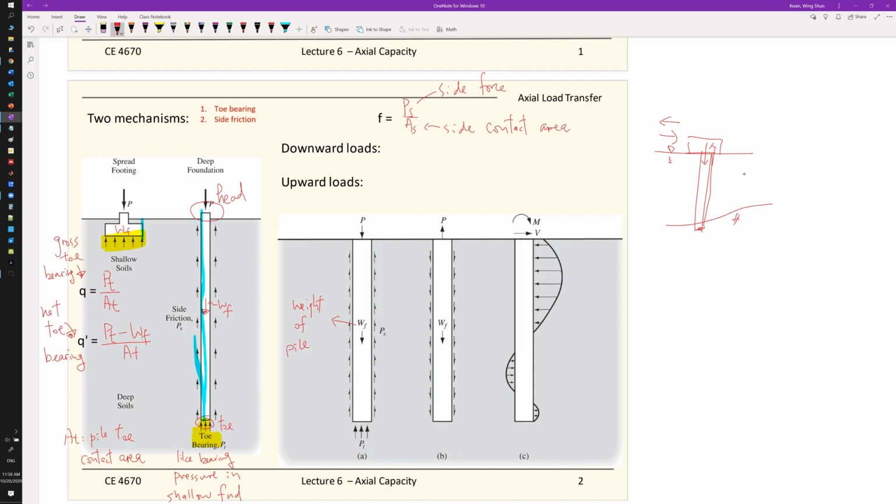So if you have rectangular piles, a dual draft, or circular steel piles, then that's the way you calculate your side area based on your geometry. And this F here is the side friction. But very important, there's a concept you need to accept: this is not a static friction. This is dynamic friction, because when you drive the piles, you mobilize the soil around it. So this is a mobilized side friction. We'll talk about this. This is displacement dependent.